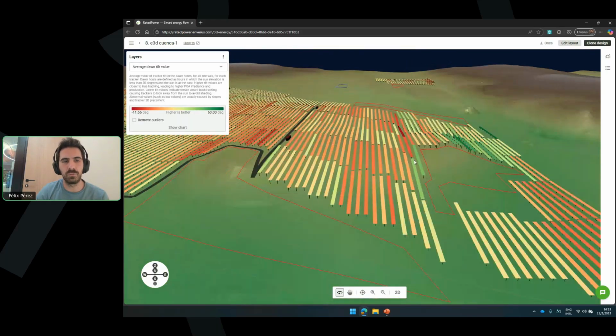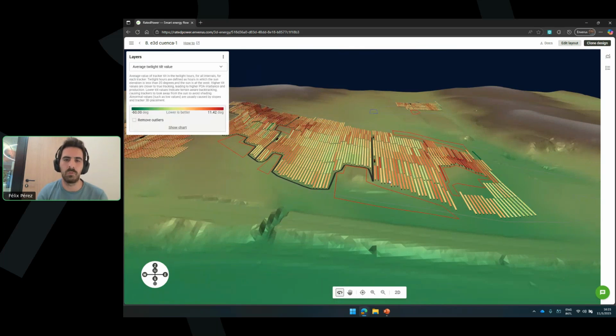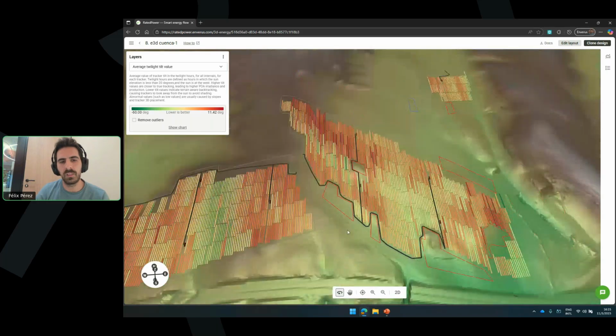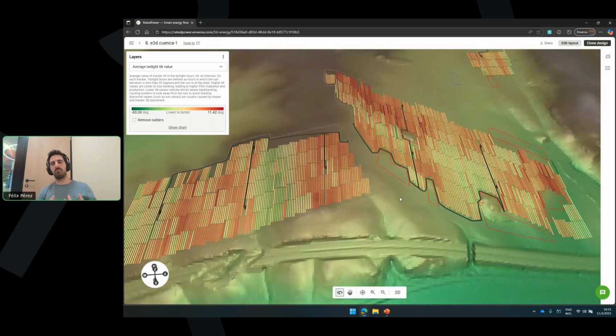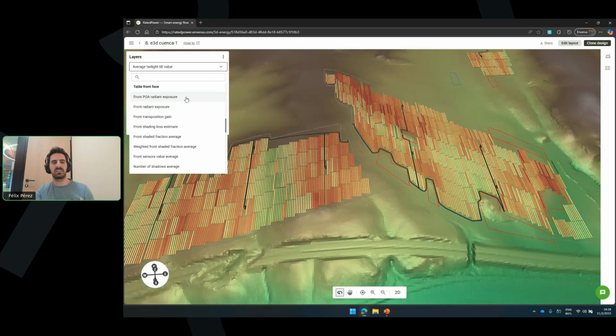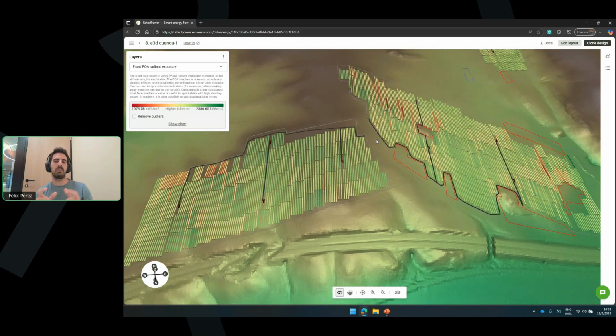And you can see the same thing for the afternoon, and it's more or less the opposite, right? But of course, there will be differences. You see how in this tool, we can manually set the tracking angles for individual trackers. That has an impact on POA, on the production, and on the production of each individual PV module, right? We may also even have situations where the terrain-aware tracking is failing a bit because sometimes shadows can't be avoided, and that will have an impact on the PV module production, right?